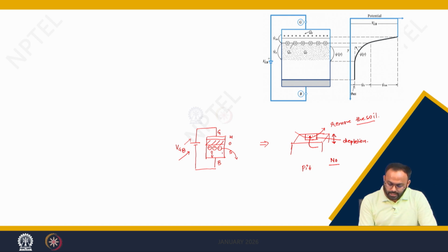So this is similar to when you apply the gate voltage: there will be a depletion region, then increasing the gate voltage will increase the depletion region thickness, and this depletion region thickness will get stopped after a certain value, and then inversion charge will come into the picture. These inversion charges are nothing but taken from the body itself, which are minority charge carriers, correct.